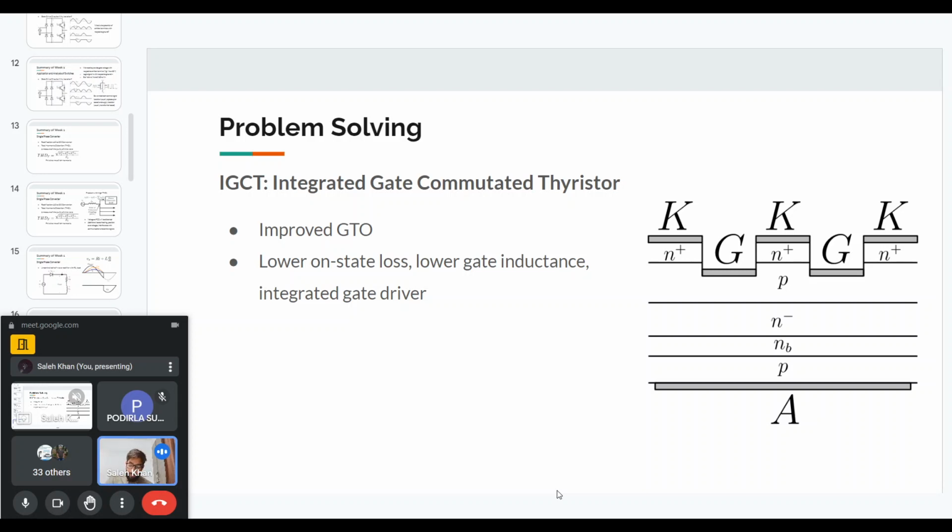So the limits for THD are given by IEEE, which will provide you the standards. Actually they have very detailed limits for different harmonic levels. From, let's say, the second harmonic to some order of harmonics, they will have one limit, some percentage. It cannot go beyond that percent, and after that harmonic it will be a lower percentage,